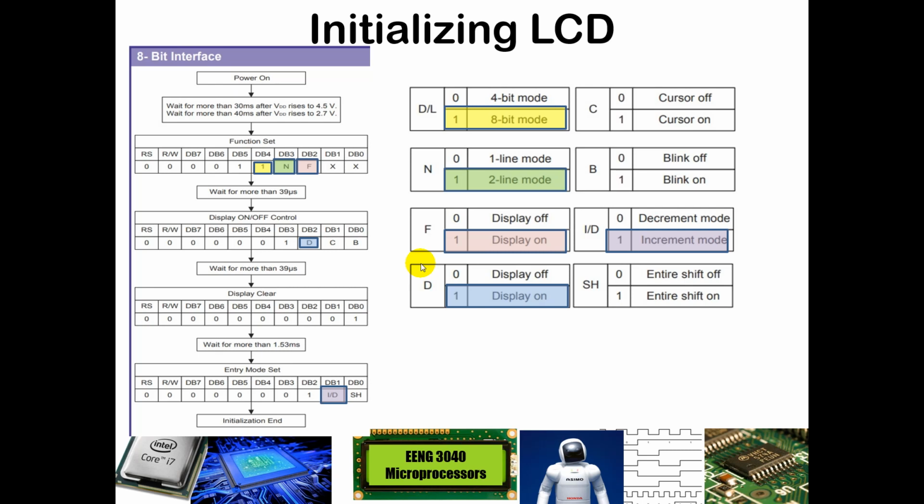The first thing is a function set, and so with that you're setting it up for 8-bit mode. So this LCD can actually be programmed with either 4-bit or 8-bit instructions. 8-bit instructions is what we're using because we're using this I/O expander, which allows us to put out all 8 bits at a time. 4-bit mode is also commonly used with LCDs, and largely it means you have to send one nibble at a time rather than the entire byte of command or data.